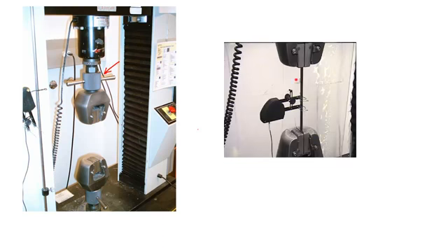This is a picture of another device, same type, same idea, but this one is electromechanical. It doesn't need fluid pressure to provide the force to pull apart materials, but here you can see hand-tightening grips. And here's a picture with a carbon composite specimen put inside for a tension test, and then you can see the extensometer right here clipped at these two points.